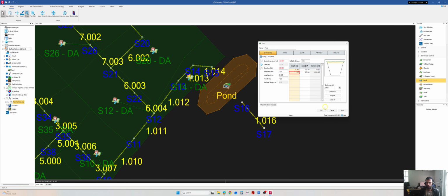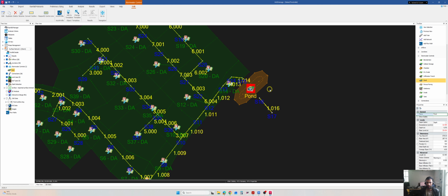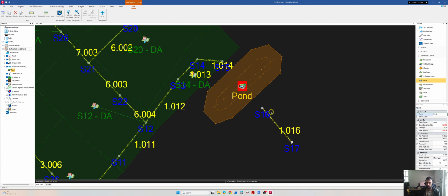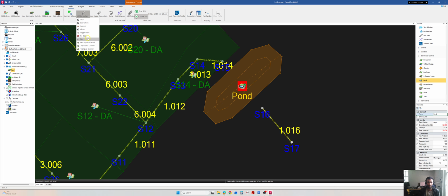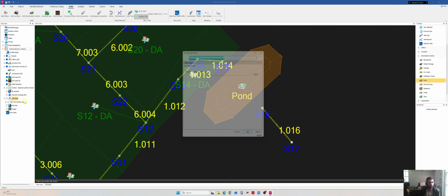So our pond is ready, now we need to connect the inlets and then the outlet. We can do it directly from the build tool, like we can just add a pipe and click here, or I also have the CAD data for the layout where we can do the connections. In this way we will also see how we can import the shape files.